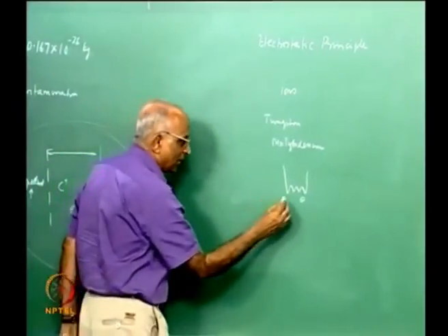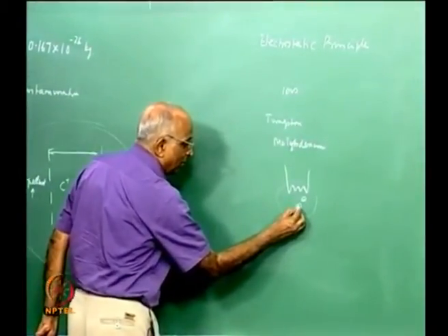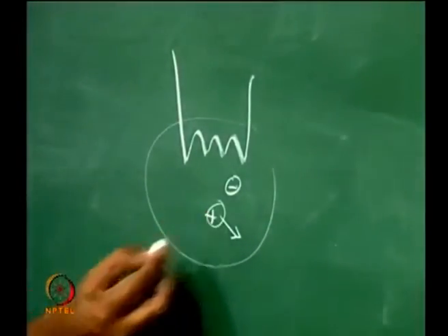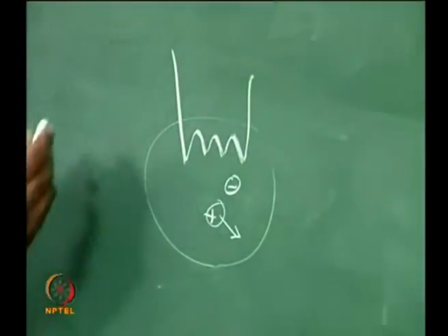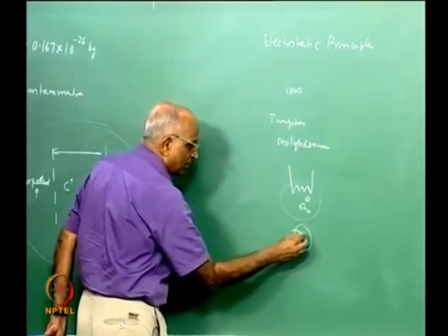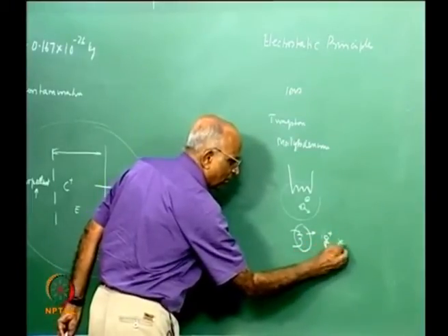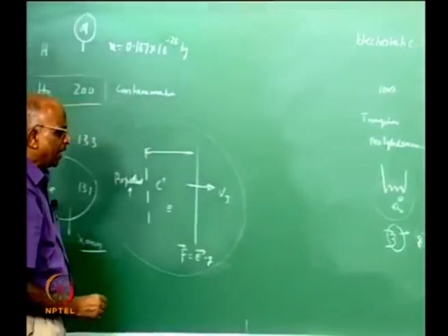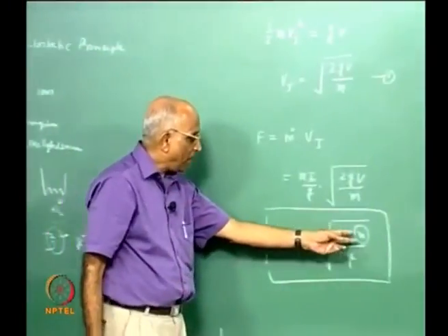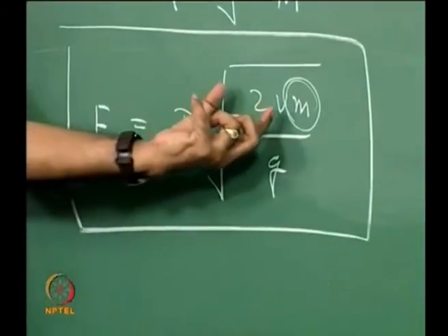When it gives out the electrons and you have a medium like xenon gas surrounding it, when an electron hits a xenon neutral atom, it dislodges one more electron from it and the atom gets positively charged. Therefore it is easy to make use of: you heat tungsten, you put the tungsten in a medium of xenon, and it is possible to get positively charged particles of xenon coming over here. At this point in time, I must also tell you, we talked in terms of the molecular mass of the propellant used for electrostatic propulsion being large.